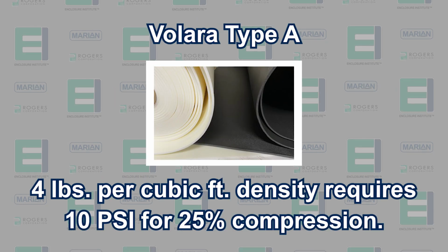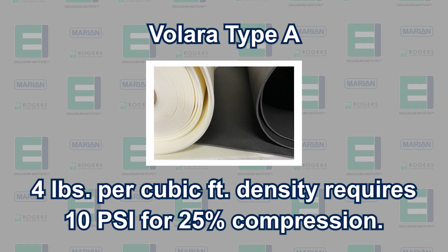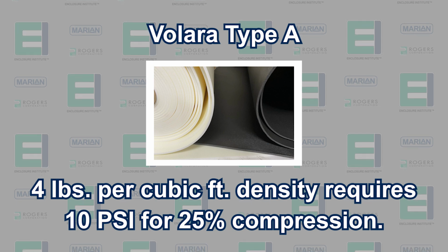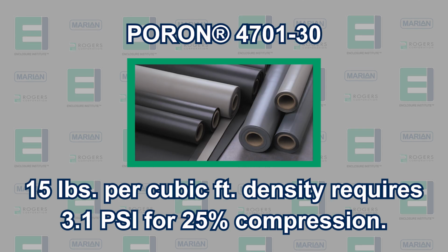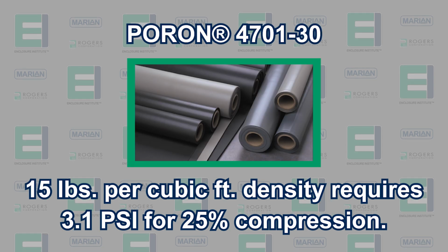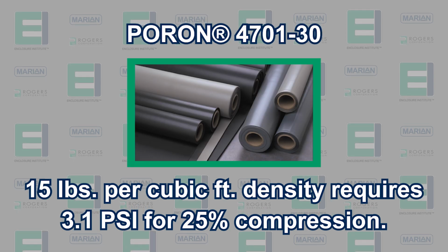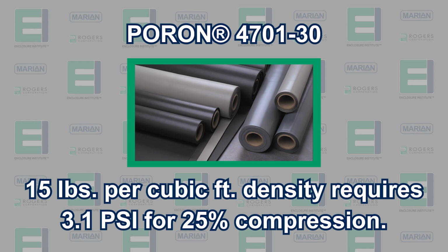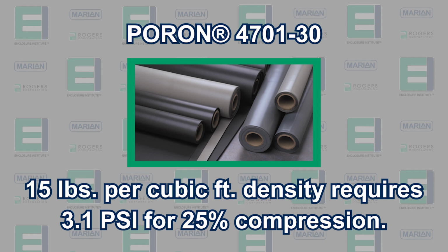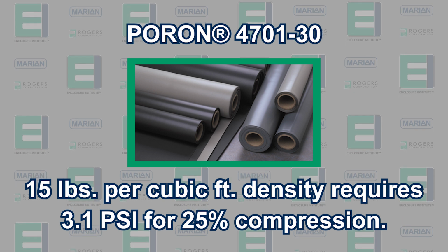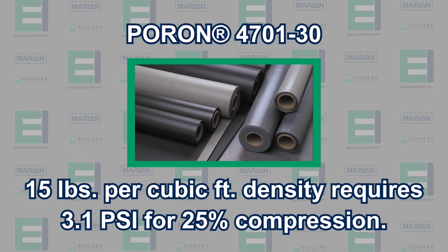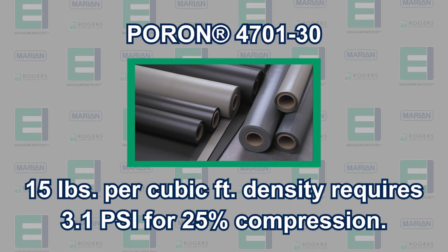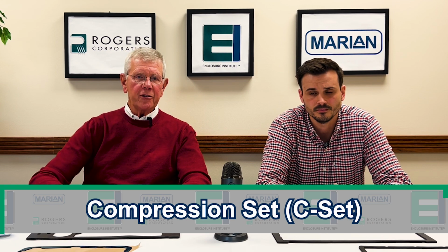For example, Velara Type A, a cross-linked polyethylene foam at 4 pounds per cubic foot density, requires 10 psi for a 25% compression. Compare that to PORON in formulation 4701-30, a high-density urethane foam, which is 15 pounds per cubic foot density, more than 3 times heavier than the Velara, yet it only requires 3.1 psi for 25% compression, which is 3 times less than the 4-pound Velara. Let's talk about compression set next.